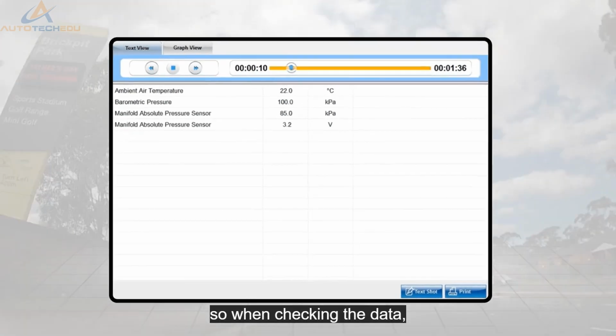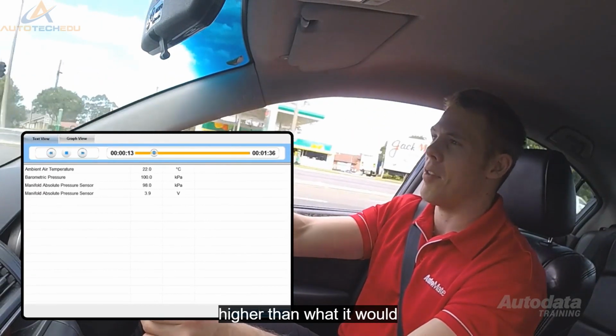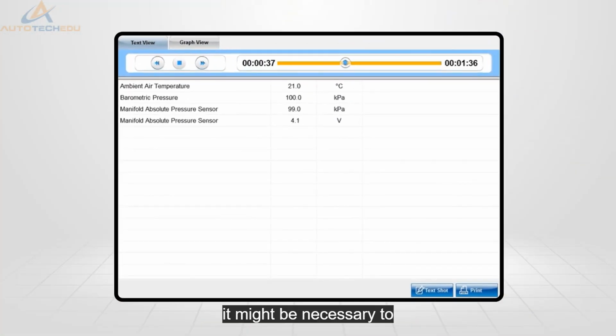So when checking the data, keep this in mind. At idle, the vacuum reading will be higher than what it would be at wide open throttle. It can be even higher again on deceleration. It might be necessary to get another tech to drive while you watch the data.